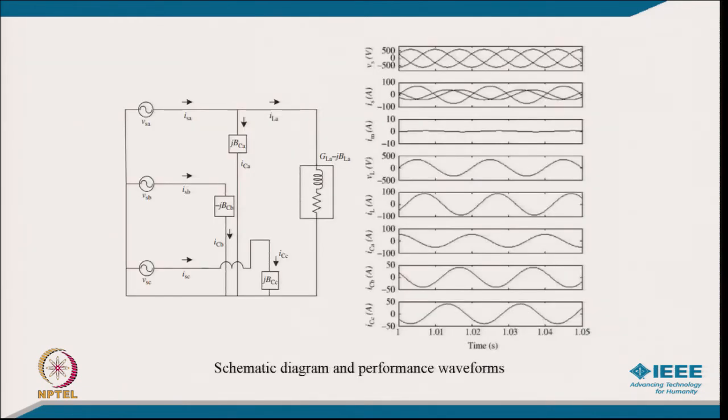So, this is typical here. In this example, the load is connected between A phase and neutral, and it is an inductive load. Then of course, with this compensator value we have to make the power factor unity, and after that we have to use two other compensators to make this neutral current 0. So, that is required to realize it as a unity power factor load on the supply and make the neutral current 0.